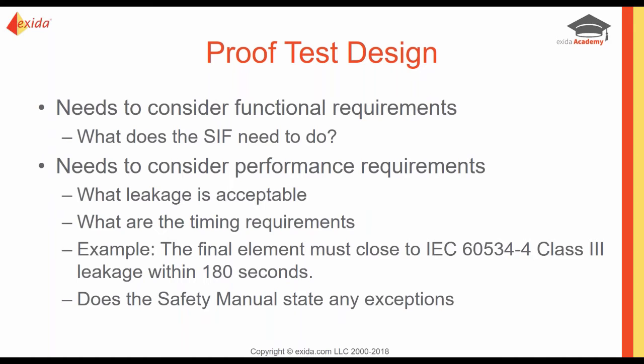Great. Is that all of the information you need? No, you also need to consider the performance requirements. What do you need to know about that valve shutting? Well, is there any leakage that's acceptable? Are there any timing requirements? For example, you might have a final element that needs to close per the standard IEC 60534, class 3 leakage within 180 seconds.